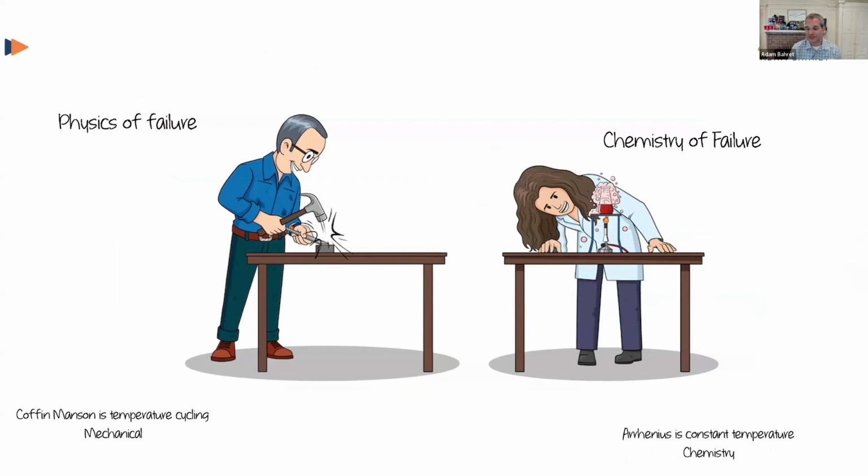Like I said, it's very surgical, in the sense that you are, in advance, very carefully diagnosing and characterizing what the wear out failure modes are. If we're talking about compressing this in time, by taking elevated stresses to compress it, we need to understand what we're working with. A lot of times we use the term physics of failure generically for understanding the mechanisms that make something fail. But in this case, I like to use two terms, physics of failure and chemistry of failure, because it is very important to distinguish which you're dealing with before you begin to construct your model.